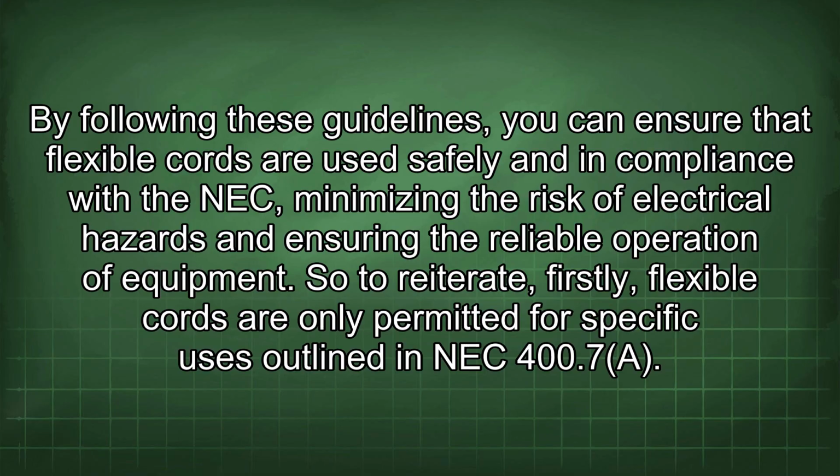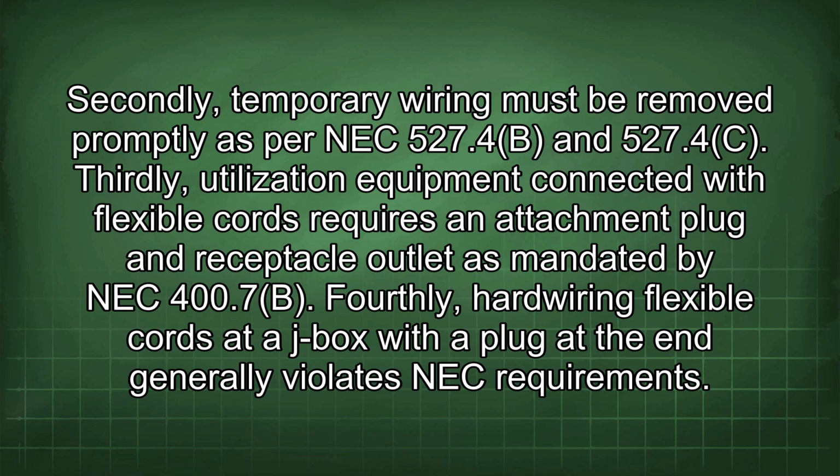So to reiterate, firstly, flexible cords are only permitted for specific uses outlined in NEC 400.7(A). Secondly, temporary wiring must be removed promptly as per NEC 527.4(B) and 527.4(C). Thirdly, utilization equipment connected with flexible cords requires an attachment plug and receptacle outlet as mandated by NEC 400.7(B).